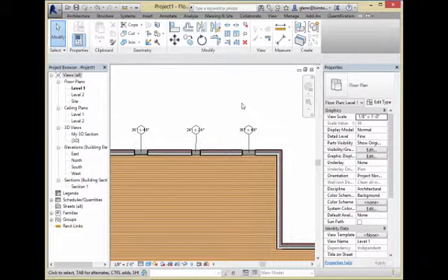What they actually meant? Yeah, no worries. As we start changing the tags to show other information, they get more interesting. Yeah, because those numbers were pre-assigned numbers for these doors and windows, and you never assigned them, so they don't really correspond to each other. They didn't mean anything to you. It gets more interesting if you start changing the numbers, like for the doors or windows, I'll make them A, B, C, and then it'll make more sense. But it's all about just changing the values in the database. No worries. Okay, those are the biggies.